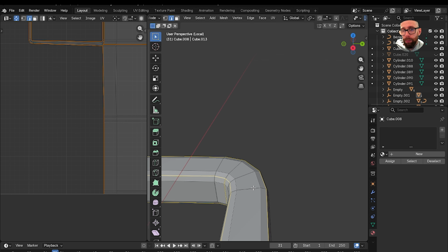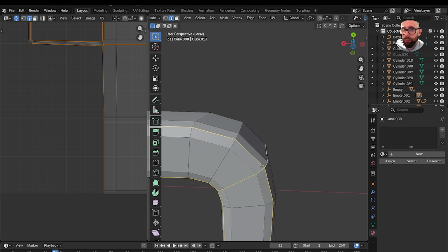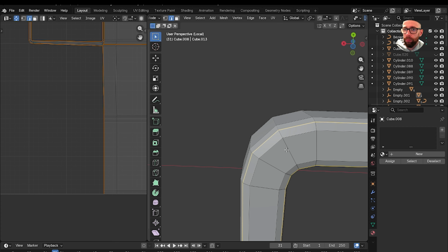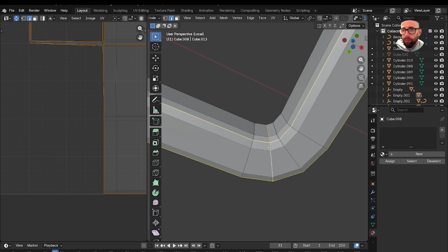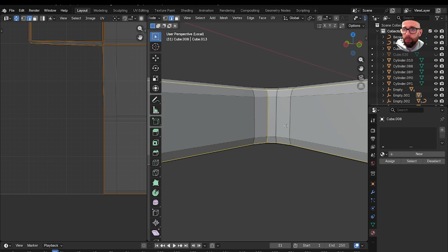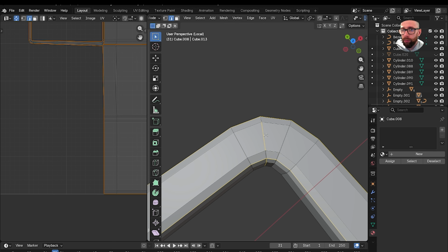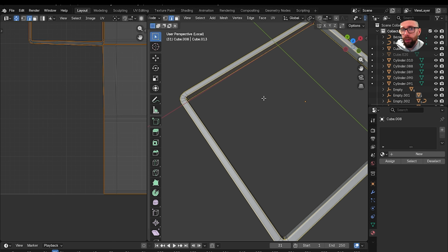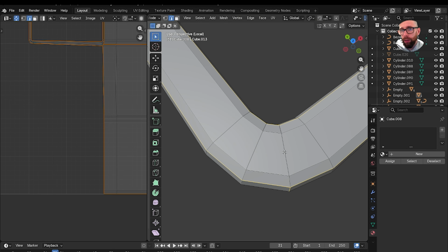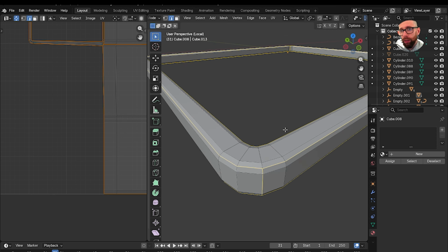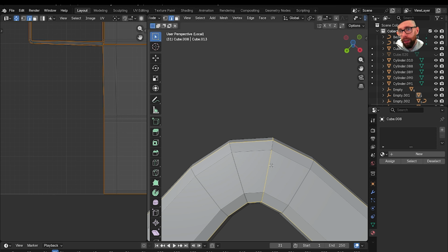We don't want the top and the bottom bit done. So we got that, and then we drop this corner we haven't done. Again, all I'm doing is I'm holding down Shift and Alt, and then holding down Shift and then deselecting the ones I don't want. Right click and mark seam.